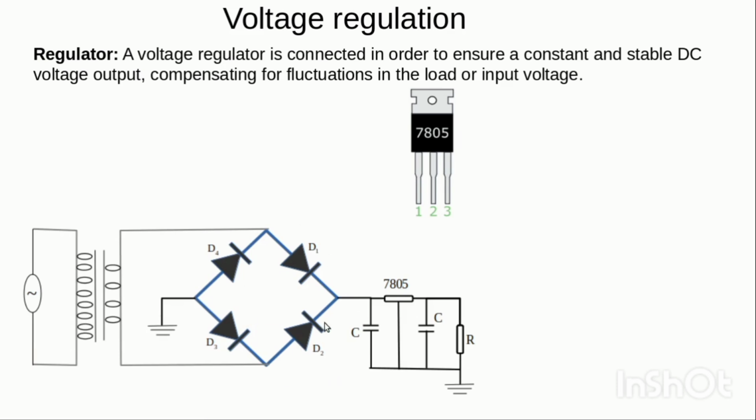So we have the setup in this form. We have our initial capacitor. This is the regulator. This part is connected to this one. This one is connected to the ground, while this other part is connected to the output. It is also advisable to add another capacitor here, just to serve as filtering to smoothen any possible fluctuation, right? So we have this particular shape initially, right?